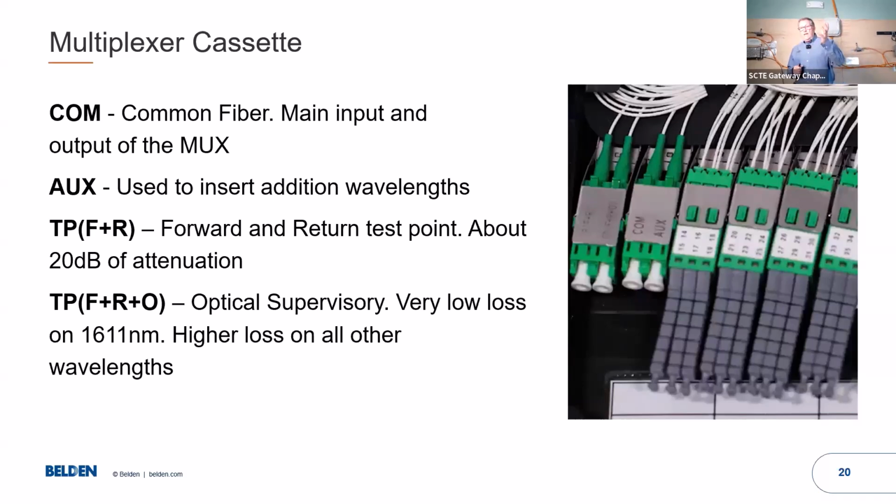You can take a DWDM mux and a CWDM mux, put the CWDM into the auxiliary port, the expansion port, and that DWDM mux is now putting out both sets of channels. So it's a way where you can expand. If you had a 12-channel mux and you wanted to make a 36, you could add another mux and daisy chain them together. That's what that port's for.